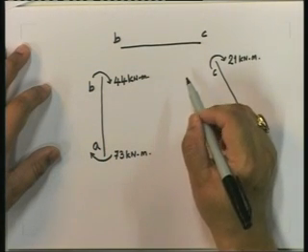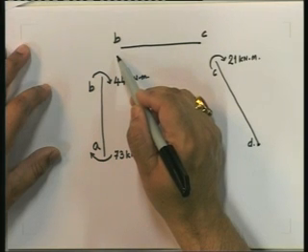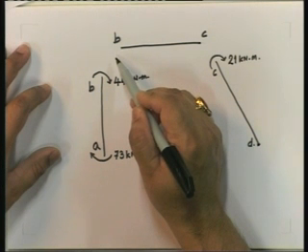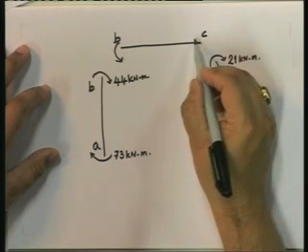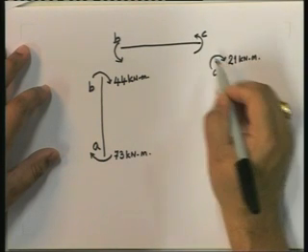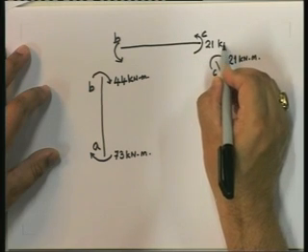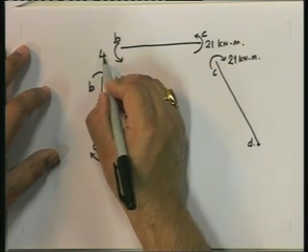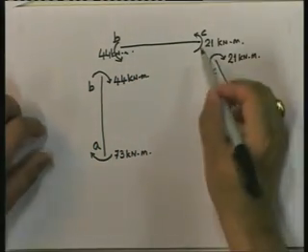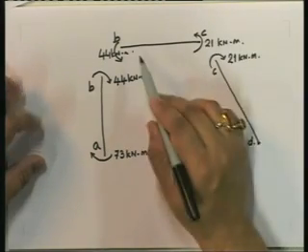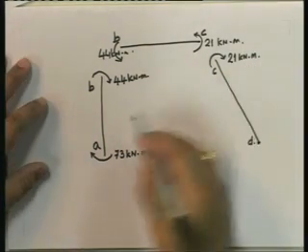But you see, there is no moment at this particular point. So since there is no moment at that particular point, for BC we can find out the member end moments purely from equilibrium. Since I have 44 over here, from equilibrium this will have to be 44. Here again from equilibrium this has to be 21 kilonewton meter. This has to be 44 kilonewton meter. So I know that these are going to be the moments.